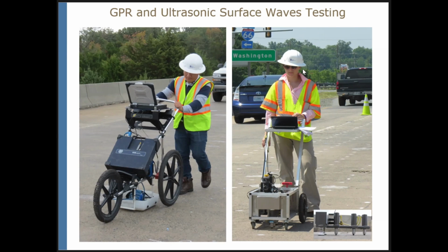The method is such that you can describe it more as a qualitative method, because you are never certain, for example, is there maybe delamination there? Is it just a corrosive environment or something else? But high attenuation is typically an indication of some deterioration processes. On the right side is a quantitative method.